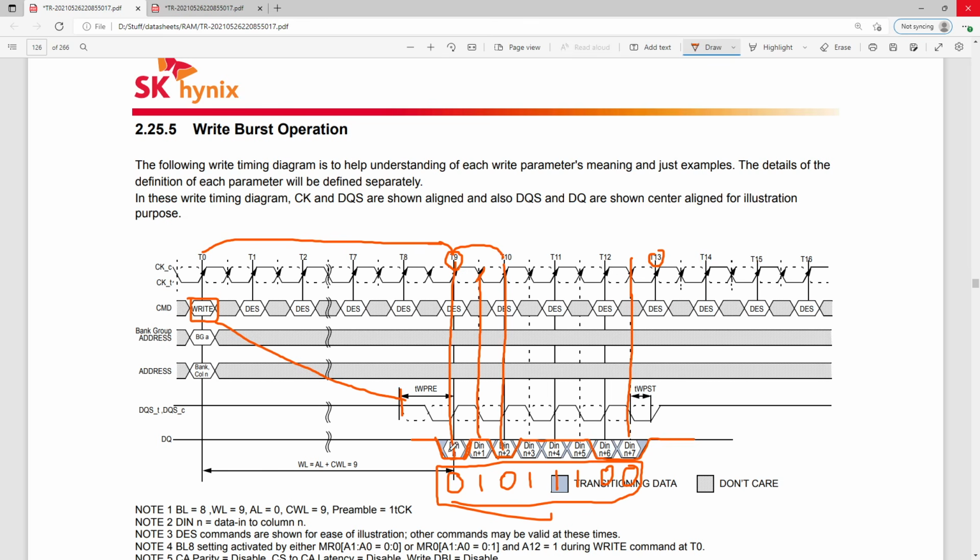And the memory controller is doing the difficult task of outputting the data ahead of the actual clock edges. Because if you had this transition point on the clock edge and the memory chip went to sample that transition point, in a perfect world it would measure a voltage level halfway between a high and a low. That's neither a 1 nor a 0, and things would get very awkward. So the memory controller has to deal with shifting the data relative to the clock in order for the memory chip to be able to just check what's on the data queue at the clock edge.